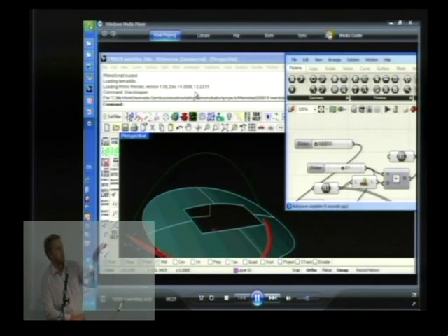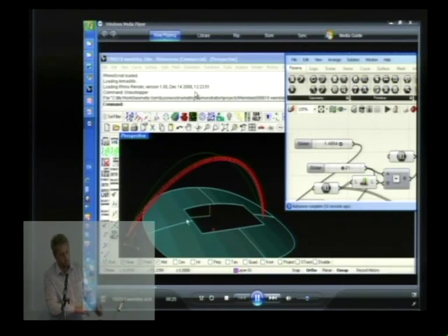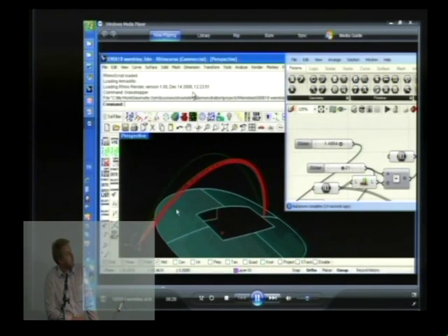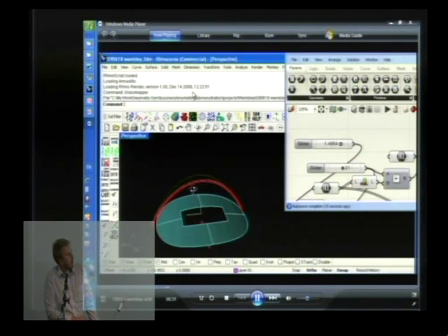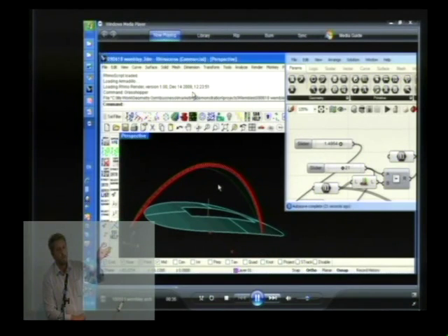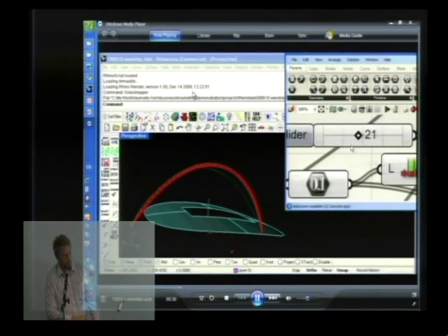And the arch tipping backwards stops the roof falling in, and the roof trying to fall in stops the arch from tipping over backwards. So it is a big counterbalance for the roof sitting over the seats. So of course you could explore the best inclination angle for that arch to meet that counterbalance.